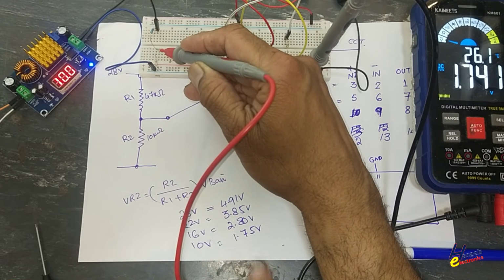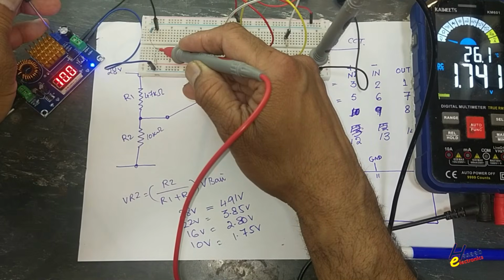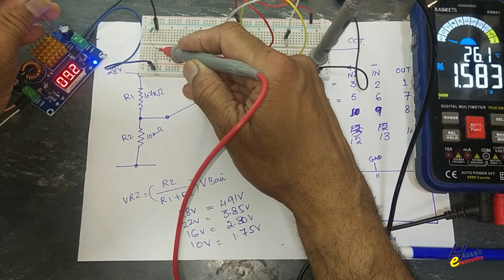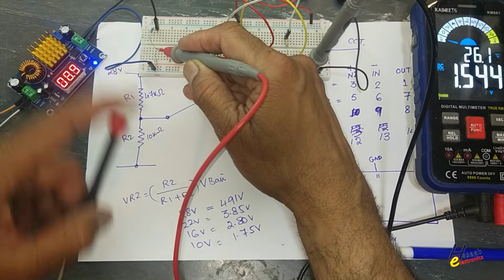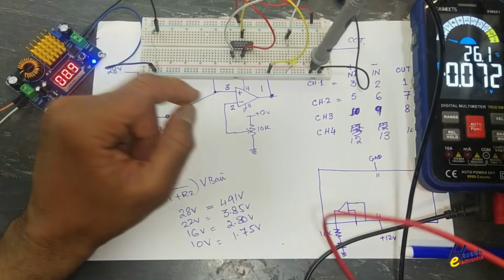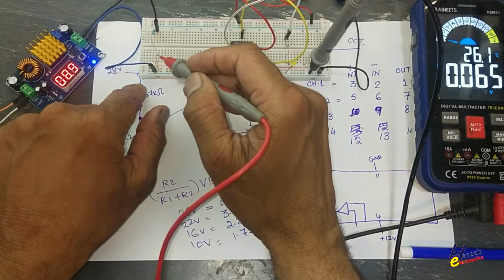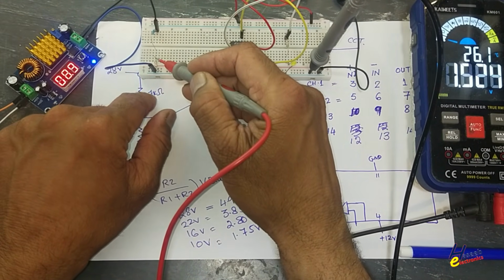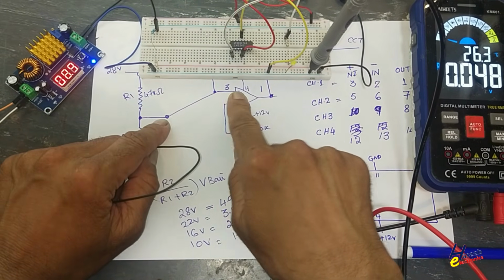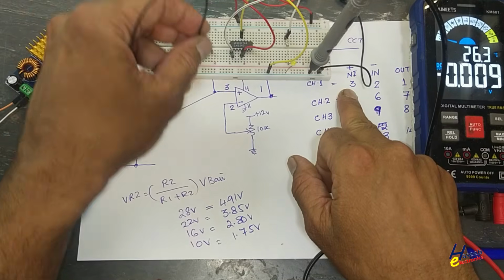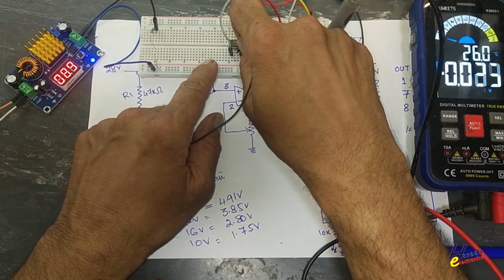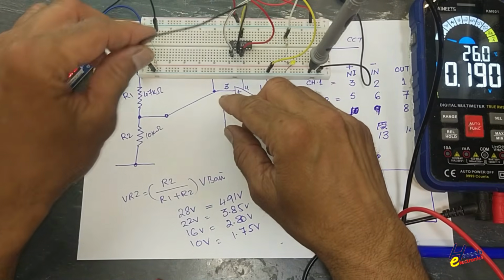Same this one. We will decrease it now less than this level. Let's suppose battery is approximately 9 volts. That time we have scaled output 1.5 volt. We will feed this input to pin number 3, that is non-inverting input. Non-inverting inputs are our sense signals.